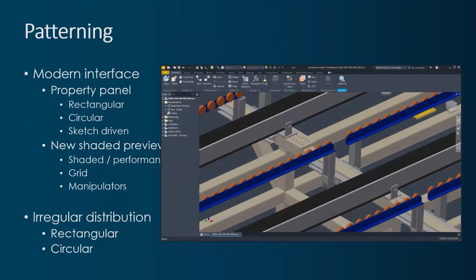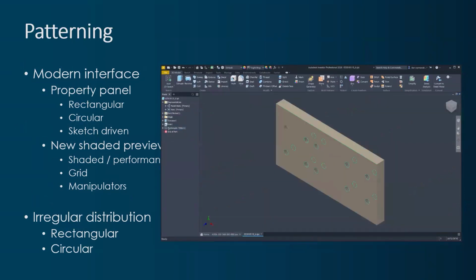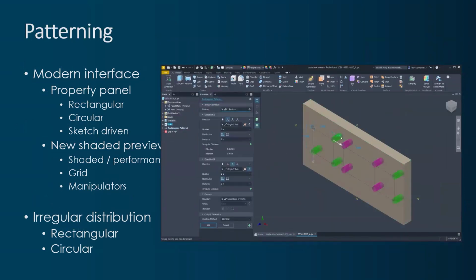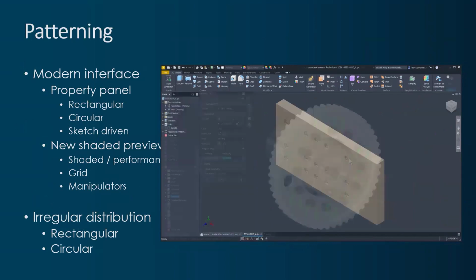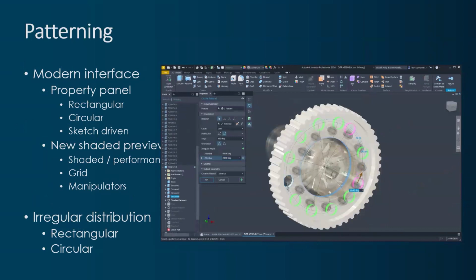So yeah, quite a nice bunch of options that we can now go and use the patterning dialog to allow us to change the instance positions. So you'll see there we've got this option on the dialog now for a regular distance, and that simply allows us to go and set instance or irregular spacings both in circular and rectangular patterns for each of these options.